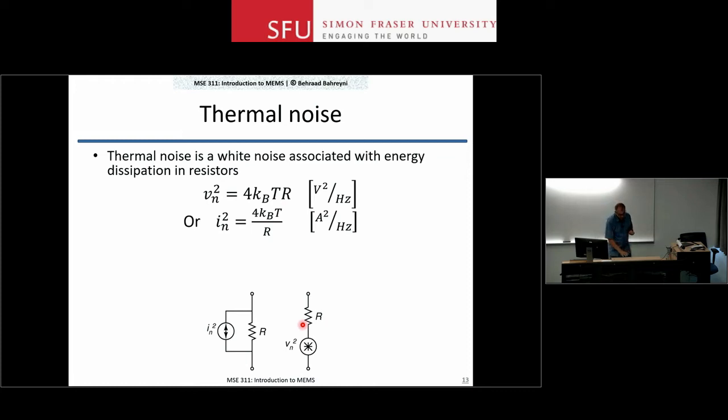How much is that voltage? Well, you can estimate it from this expression here. I can model it using a voltage source in series with my resistor. Now this resistor is ideal and noiseless. All the noise is represented by this voltage source.